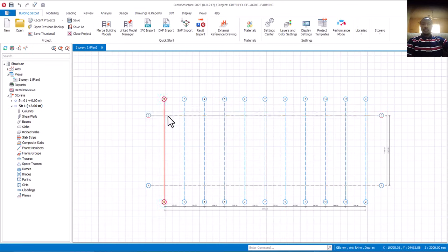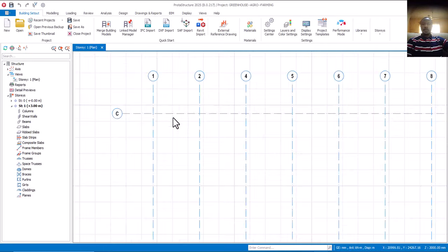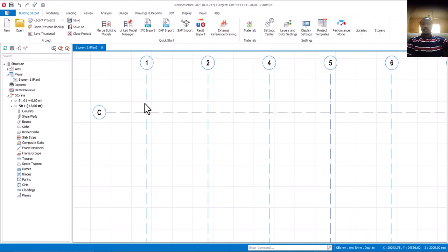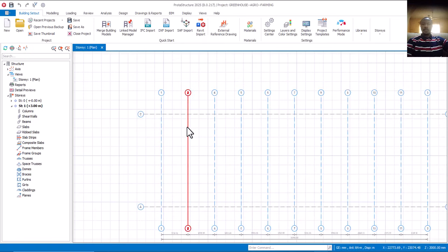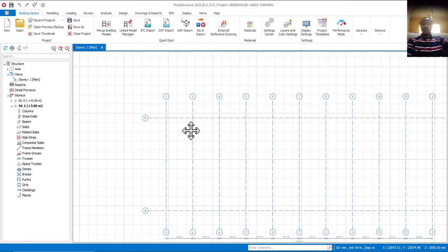All right, so I haven't done this one now. You notice that I use beam along this part. Using a beam along this part, yes, it's fine, but for me it's a waste of materials, because I can use my pedestal here. I can use my pedestal for each of them. You can imagine the kind of concrete between this place and this place. That's a waste of material, of resources. That's for me. But if they want beam, why not? If they only provide beam, then we are going to provide our beams.